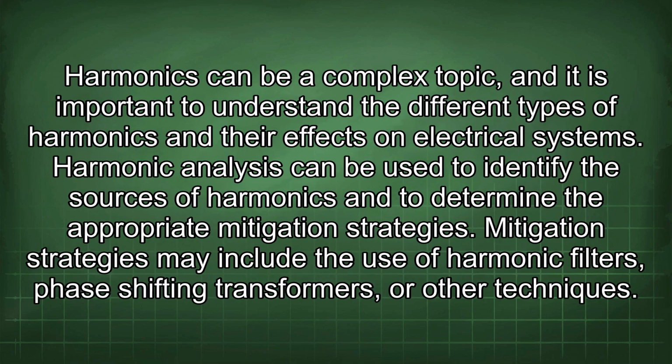Harmonics can be a complex topic, and it is important to understand the different types of harmonics and their effects on electrical systems. Harmonic analysis can be used to identify the sources of harmonics and to determine the appropriate mitigation strategies. Mitigation strategies may include the use of harmonic filters, phase-shifting transformers, or other techniques.